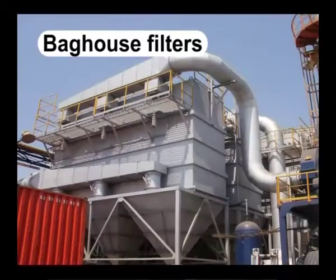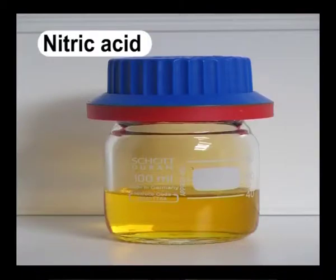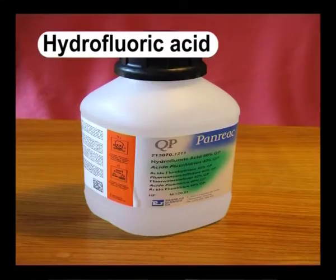A number of processes are involved in the cleaning up of flue gas. The mixture of flue gas is collected by means of particle filtration, and this filtration is conducted using electrostatic precipitators and baghouse filters. Baghouses are very effective for fine particles. The next step of the processing and cleaning of the flue gas is processing by scrubbers, which are critical for the removal of hydrochloric acid, nitric acid, mercury, hydrofluoric acid, lead and residual heavy metals. With the reaction of lime, sulfur is converted into gypsum. The wastewater which comes out of the scrubbers is then passed through a wastewater treatment plant.